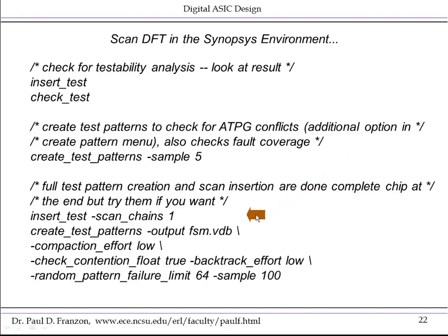Another thing the design engineer has to consider is how many scan chains are going to be supported. Each scan chain has to connect to its own set of pins. So the more scan chains you have, the more pins at least have to be dedicated to or multiplexed for test support. But also, the more scan chains you have, the less time it will take to test the chip. So there is a trade-off here.